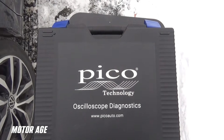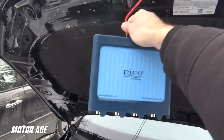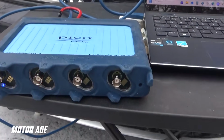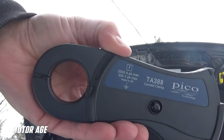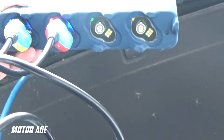And this is where the power of a lab scope, specifically a PC-based lab scope like that of Pico 4425A, comes in. The hardware of the scope, along with the software, will allow us to capture information over a ton of time, days of time, if we choose to structure it that way. And if this information is being recorded, we simply go and find the fault and reference the information at the point that fault occurs. And there's a problem with that too. Even if I capture the fault over days and days of screen recording, how much time would it take to sift through that information to find when the fault actually set? That would be very time consuming as well.